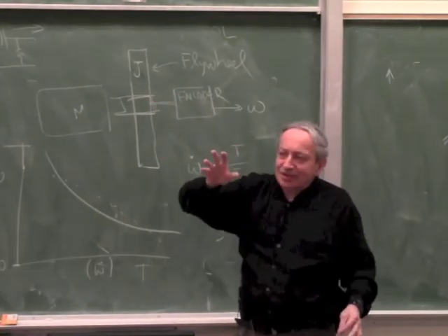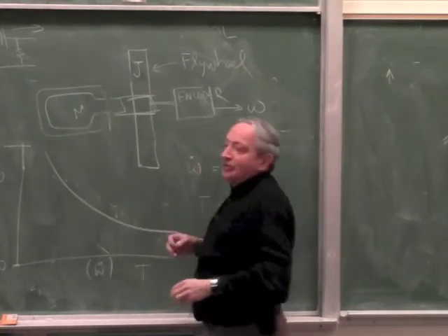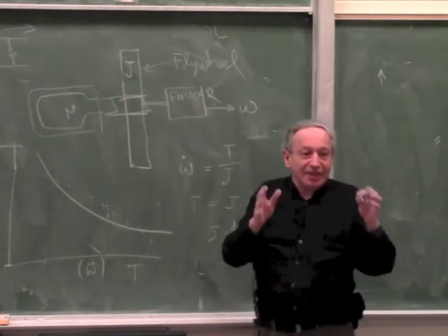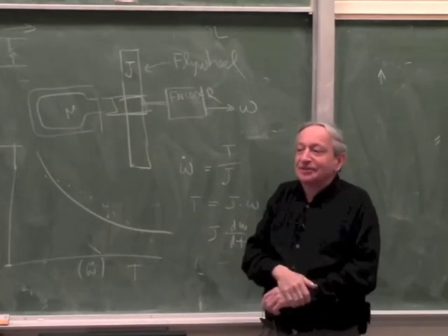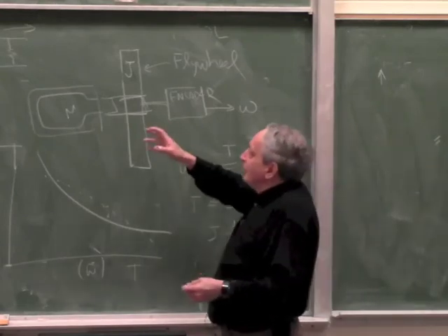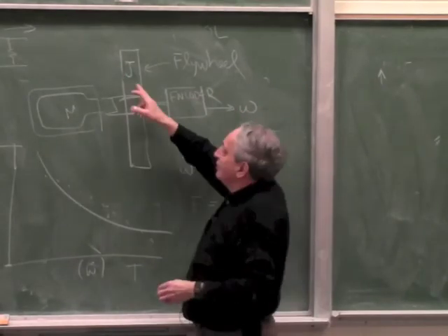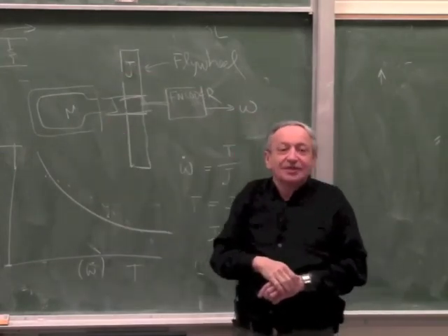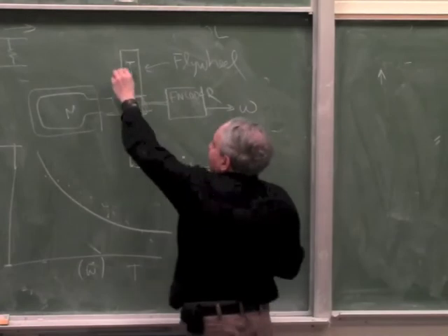Now some people say, just a minute, you don't know J because the motor has some internal inertia that you don't know. Okay? Which is true. You just know the weight that you added, but you don't know the internal inertia. So how do you get around that without complex measurements? Yeah, exactly. All you do is either add another J or do it without the J. You do two plots, one plot without the ring and one plot with the ring, because now you have one more unknown and one more equation, right?